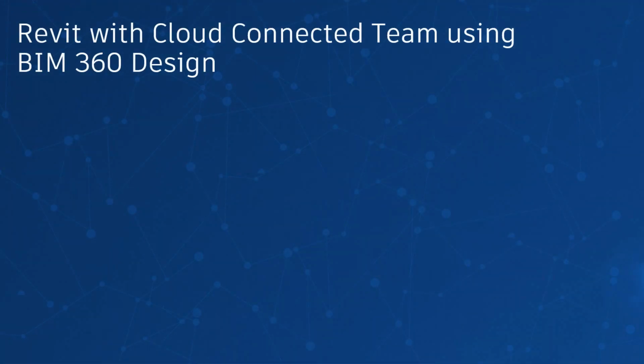We talked briefly about collaboration. So on large projects, it's probably beneficial to have everybody working in one particular file or one particular Revit model. And this is possible. We don't have to work this way. We can work with multiple Revit models and reference them into each other just like we do in AutoCAD. But from a collaboration space, what we can do is we can have a look at Revit and that cloud work sharing capability that BIM 360 Design brings to that Revit space, bringing all the teams into that one environment.